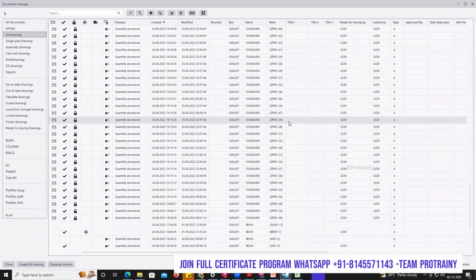For precast, you can work with Revit. For steel, you can't work with Revit. Just for commercial purposes, you can create a model and show it off like this. We are creating this mass model, we are working on that. You can create it, but from a fabrication point of view, you can't give more details specifically as per standard. You can't create and customize in Revit, but you can do it in TEKLA with the help of API developers.